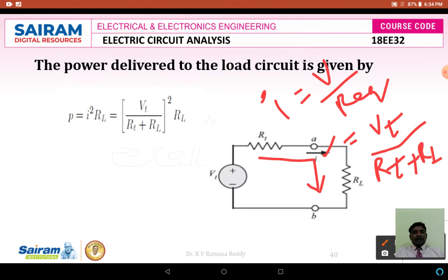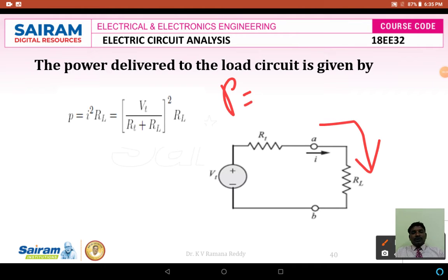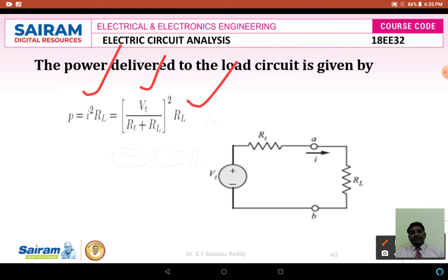If I can write that I is equal to Vt divided by RT plus RL, then what is the formula for a resistor? That is the power formula: P is equal to I square into RL. Now I am going to substitute for I, that is Vt divided by RT plus RL. Then the formula becomes P is equal to I square into RL, so substituting I, P is equal to Vt divided by RT plus RL, whole square, into RL.